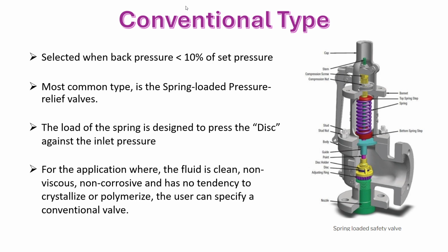Conventional safety valves are best suited for applications where the superimposed back pressure remains constant and does not exceed 10% of the set pressure.